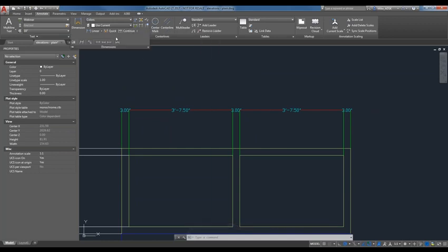That you can use. Down here, you end up with some more formatting options. So back to those tolerances, you could add them in. You also get that oblique option. You could change the text angle, so if you don't want them to be linear like this, you could edit it to change the angle of the dimension.